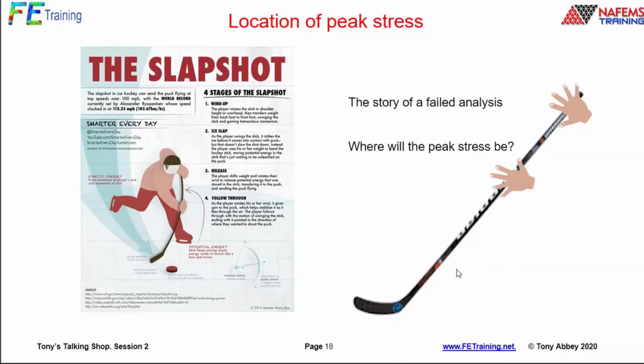So I said, well, how come they got peak stresses there? So he went and looked at the model and he said, they're using a program where they've got a transition between hex mesh down in here and tet mesh down in here, and in that transition zone, the element shapes are so horrible, it's actually creating spurious peak stress concentrations there. I said, well, surely you're not going to accept that. And he said, well, no, but I'm being overridden by the managing director because he says, well, that's where it happened on test. This is where we see it in the analysis, and that was it. So I said to the guy, okay, well, when you come back to us, I'll give you a discount on the consultancy rate.